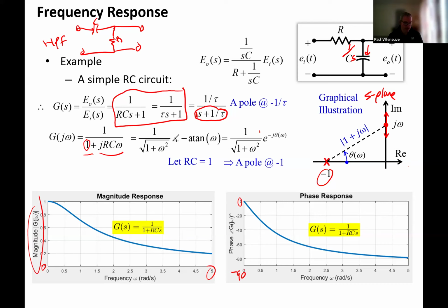And the only reason why it's not at minus 90 is because we have some resistance here. When you think about it, this value of resistance is fixed, and our capacitor value is fixed, but our frequency is increasing, so the capacitor becomes more dominant. Our X sub C is 1 over omega C, so as I increase the frequency, this goes up, this goes down, which means this impedance drops, so I have more current going through here as I continue to go on.